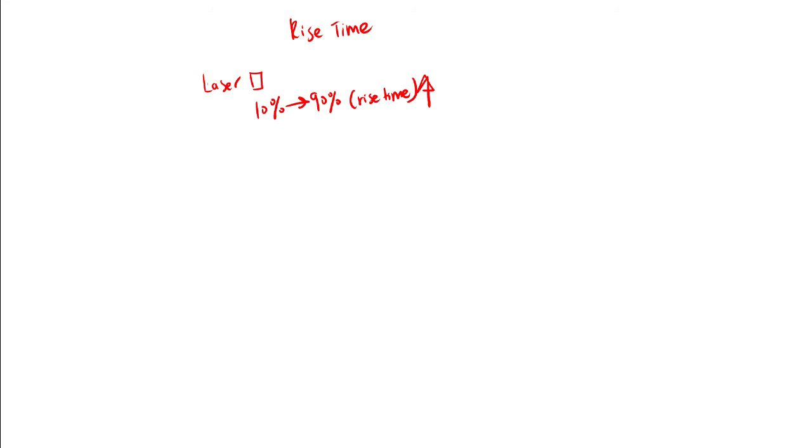On a multi-mode system, we've got a much wider spectral width with respect to the LEDs or the lasers. So there's a width of like 10 or 50 or even 100 nanometers in spectral width, and that causes what we call chromatic dispersion. So a lot of our data is being broadcast at a wavelength that is not useful. And so these various lights follow different paths, and they end up not showing up at the same time.